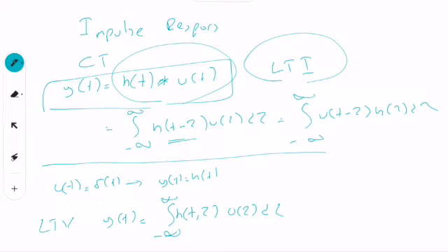But now we need to keep track of t and tau separately, because due to the time variance, your impulse response changes. Your system's response to an impulse at t equal to 0 can be different from its response when the impulse is at t equal to 10, for example. This function can capture this behavior, and we can still talk about impulse response representation for linear time varying systems. In this course, I will not cover this because we will predominantly use linear time invariant models and systems. But this is a nice and powerful feature, such that you can extend impulse response to time varying systems.